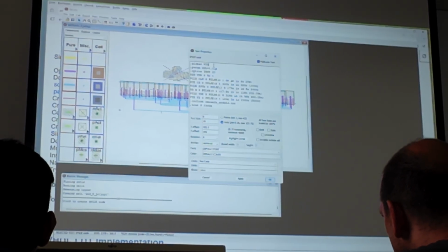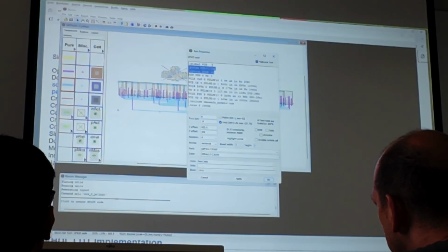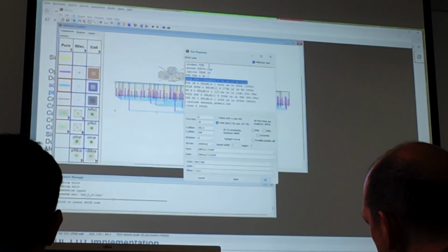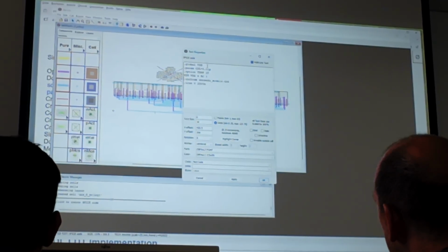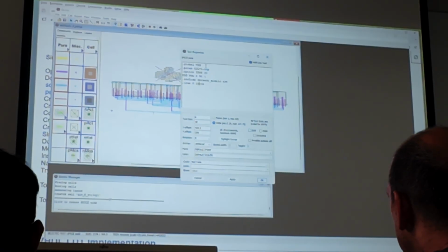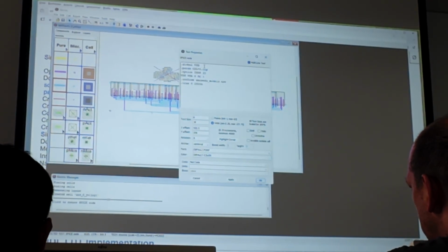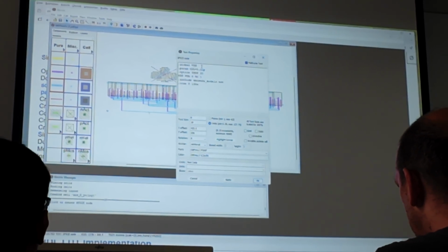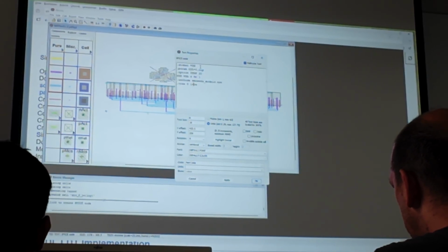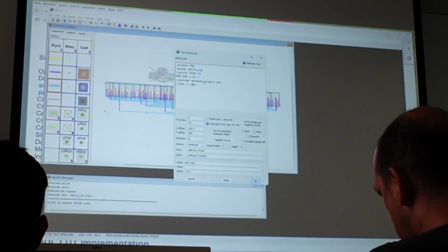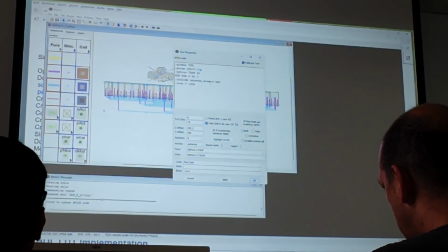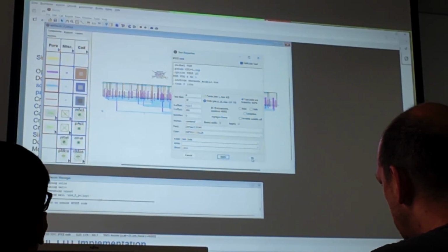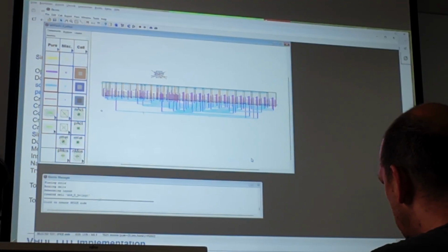So I will have my VDD, my temperature, I don't know. Okay, my clock. I will replace all these. I will have here 10 nanoseconds times 16 times. I will simulate here for 160 nanoseconds. So this will be my starting point. That I have a transistor model, CMOS edu underscore models.txt, and I have this one. Good. Now I need some input stimulus.